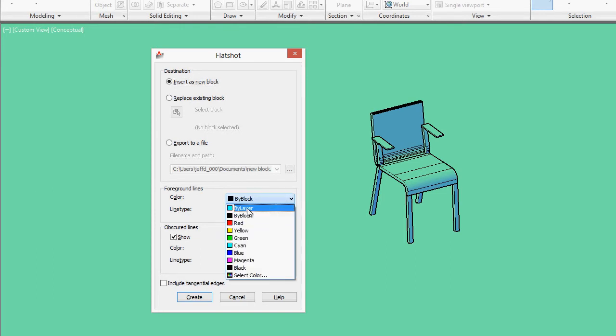You could also change it by layer, and change the layer up here and start to work with it there in order to create less work. But in the end you're going to have to assign your line weights to it, and work with the drawing and make sure that it looks like a drawing with proper line weights, and so on and so forth.